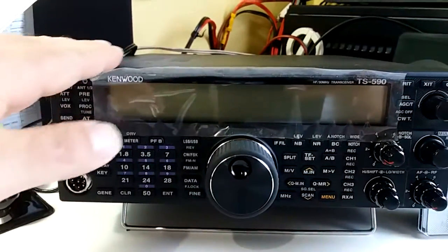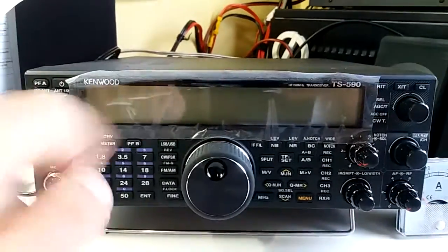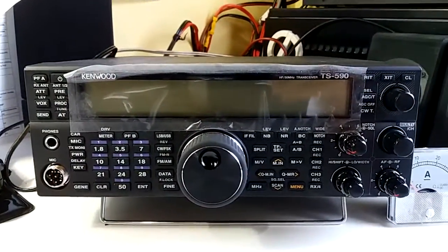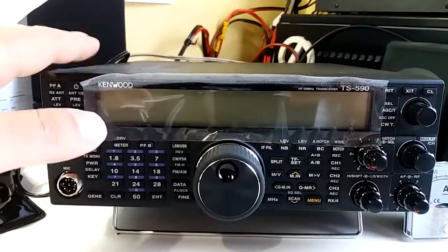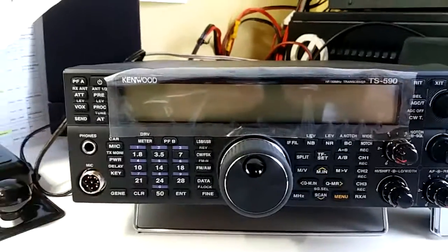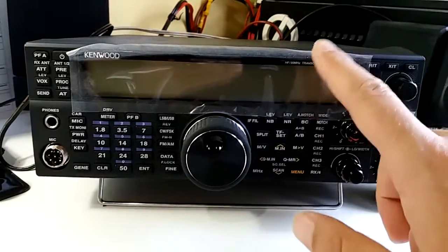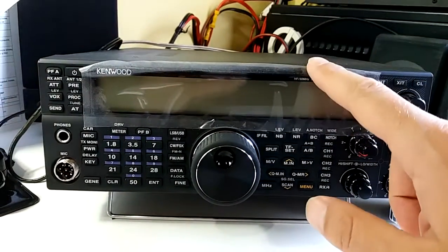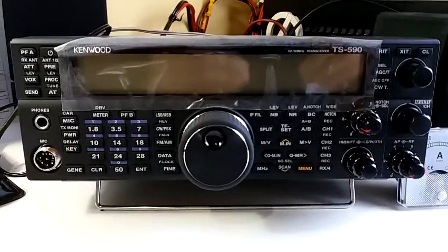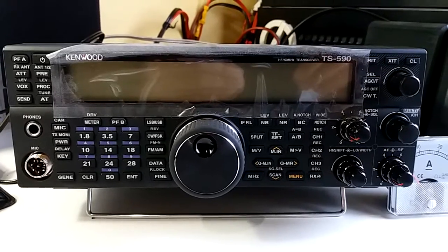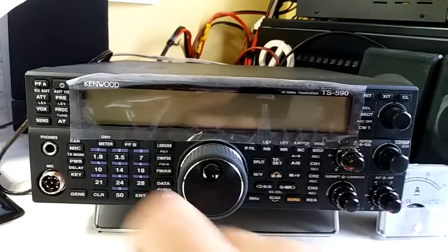Okay, the machine is off. I'm going to switch it on in 10 megahertz CW mode, and I'm going to see on FLDigi what audio pitch the CW tone appears at. The pitch tone has been set to 1 kilohertz, so I'm expecting to hear a 1 kilohertz audio signal when I'm tuned to the 10 megahertz world clock.